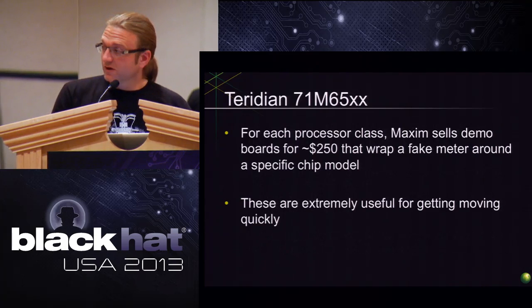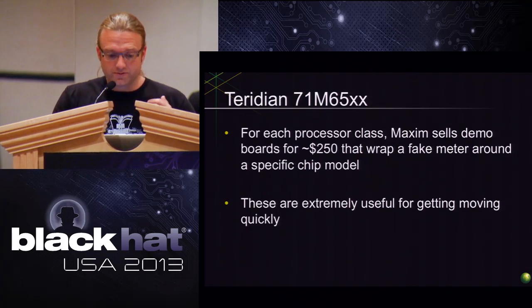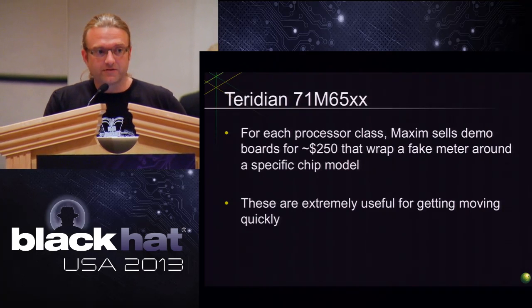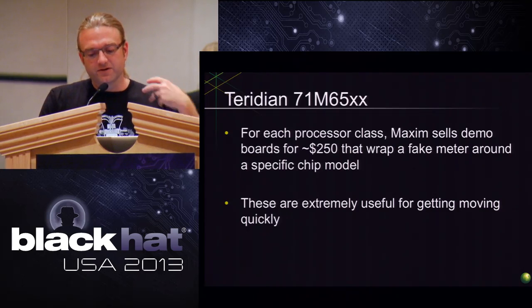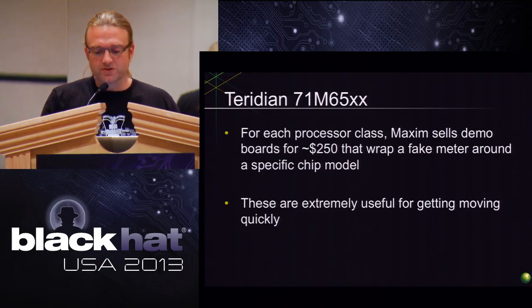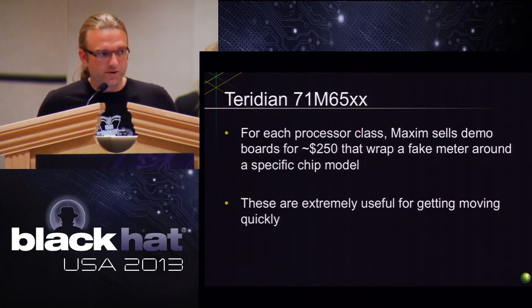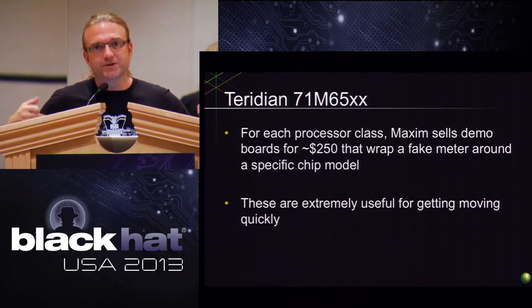A couple more pro tips. If you ever get into the space, if you ever start poking at an SoC in general, Teridian is wonderful about this. They have dev boards where they're trying to sell big vendors millions of these chips to start building hardware with. So they make a demo board that has great open source code. It's kind of open source hardware, and they're relatively cheap, so they're great because the whole chip is broken out completely already. And there's nice code so you can start figuring out what the chip is doing, at least as far as the vendor.